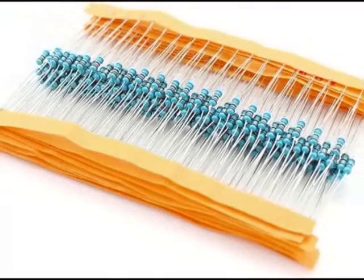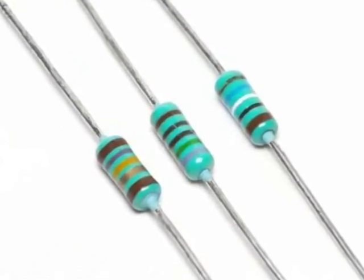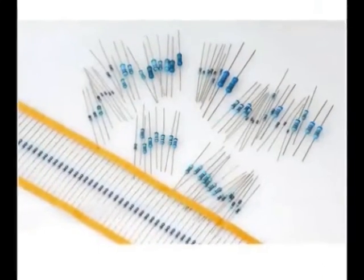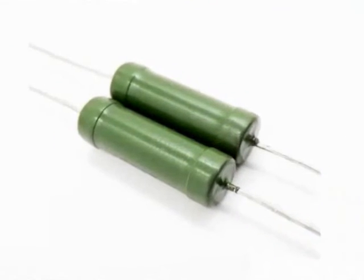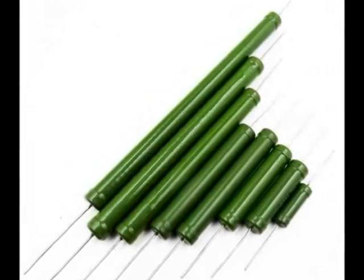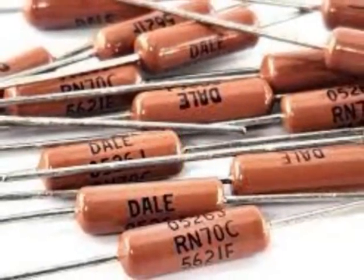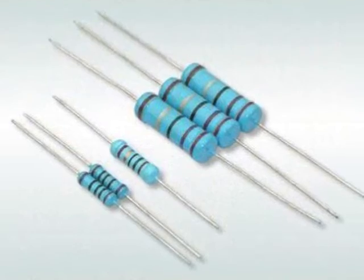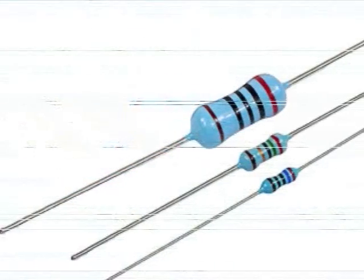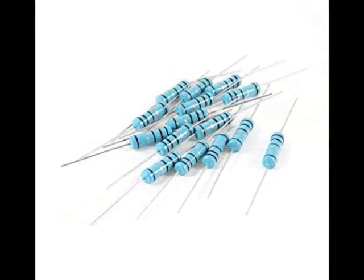Metal film resistors are named with the prefix MFR, e.g. MFR 100 ohm, and the CF prefix is used for carbon types. Metal film resistors are made in E24, 5% and 2% tolerance, E96, 1% tolerance, and E192, with 0.5%, 0.25% and 0.1% tolerance. The power rating of this type of resistors is from 0.05 watt to 0.5 watt. In general, film resistors and especially metal film resistors are used in low consumption applications.